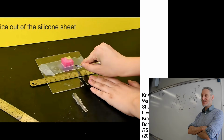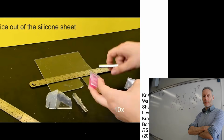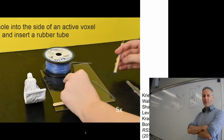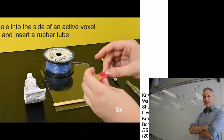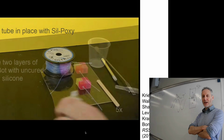The dragon skin has now set. If you leave it for long enough, it will also solidify at room temperature. Okay. Now we've got a little roll of very small tubing. We're going to thread it inside one of the voxels and seal it up. So again, it's airtight, no air escapes.